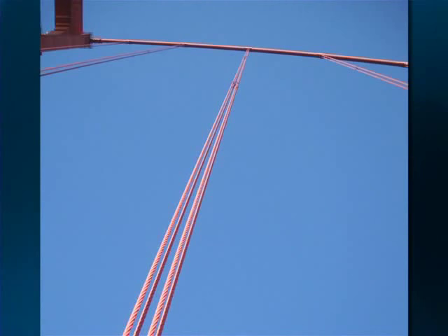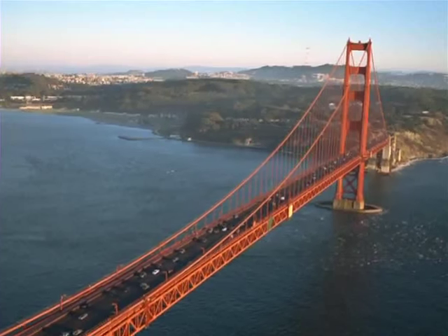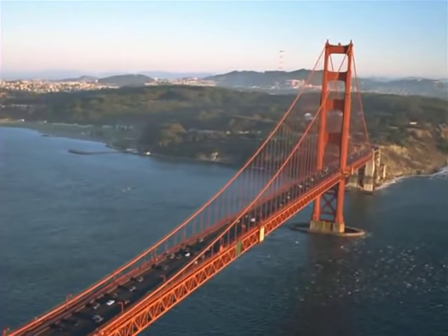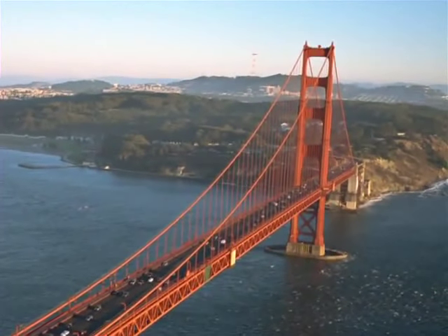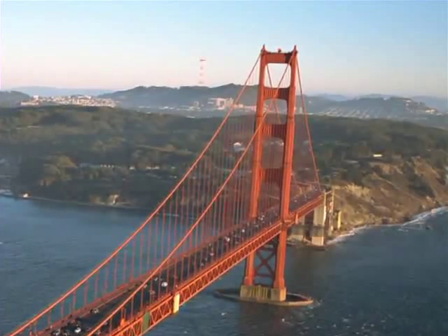Note that these members behave just like specimens in a simple tension test, except that they've been designed such that their actual stress always remains well within the elastic range of material behavior. In this lecture, we've looked at 2 great structures. Up front, we saw the Sunshine Skyway Bridge, and here we see the Golden Gate Bridge. You might have noticed that both of these examples are relatively modern, dating from the 20th century. This is no coincidence. Our main construction materials available today have significant strength in tension, but the materials available to earlier engineers, stone, brick, concrete, and wood, were much more limited in their application. Of those 4, only wood is capable of carrying significant tension forces.